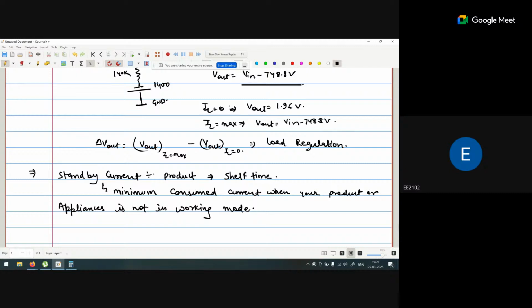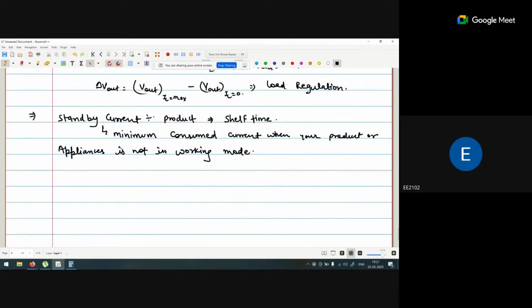So if I say, for example, I have a 500 milliampere hour battery, a 500 mAh battery, that is 60% charged. That means the overall charge is 300 mAh. So basically, it is a 300 mAh charge level. Clear?